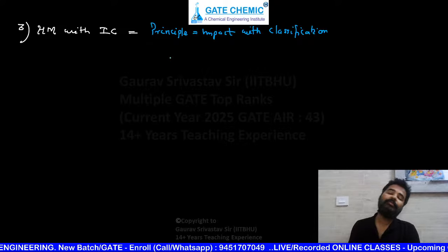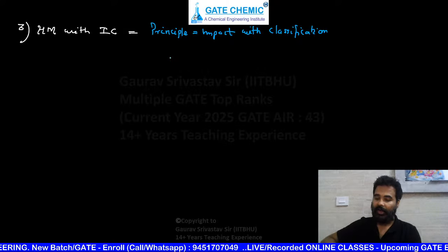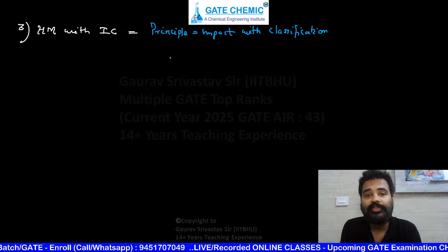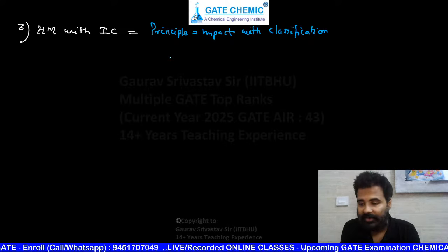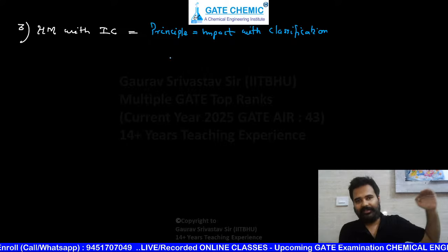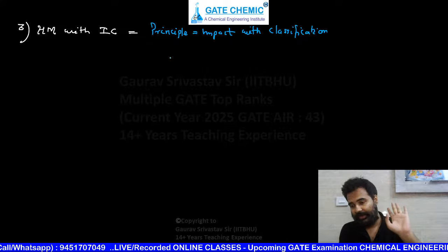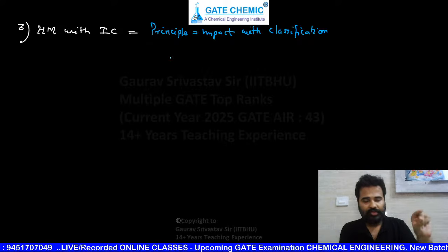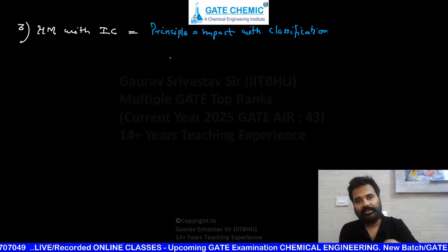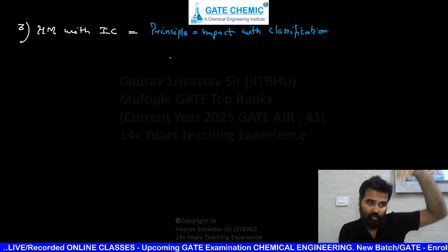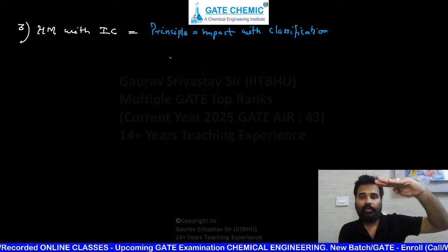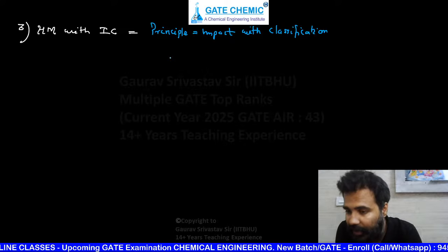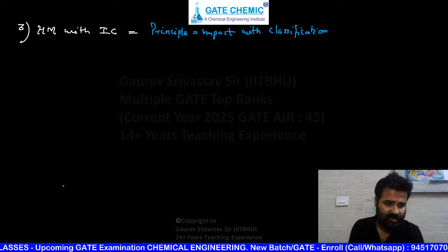You are right to ask. Beta, minus means that the product can pass through that mesh screen. If it stays on top, then we write plus. I will explain in the next lecture in the characterization of size, in the screening chapter, about what mesh number is. Minus represents that it can pass through a 325 mesh screen. Mesh number means number of holes in a linear inch. Is it clear, beta Pranjal? The number of holes in one linear inch is the mesh number. If you make 325 holes and your product can pass through those 325 holes, then it is of size minus 325. If it stays on top, then it is of size plus 325. If they are able to pass, then its size is minus 325, and if not able to pass through that 325 holes per linear inch screen, then its size is known as plus 325. Is it clear, Pranjal beta?